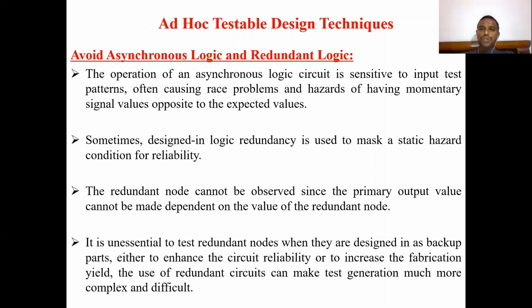If you apply some input, it may not reach the input terminal in time, so the previous value will be applied instead, and due to that we cannot get the required output. This type of problem we call race problems and hazards. The operation of an asynchronous logic circuit is sensitive to the input test patterns, often causing race problems and hazards of having momentary signal values opposite to the expected value. Then what happened here?